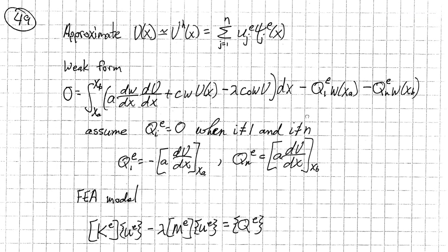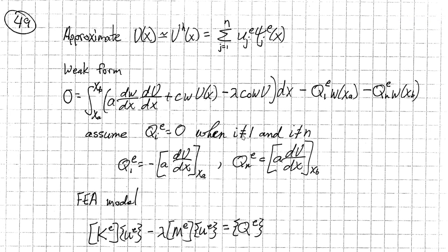So to continue on this heat transfer problem, again we're talking about approximating the solution as we've done in the past. We have some solution U, and it's the heat transfer problem, so this is our temperature. We approximate it over the finite element as a function of nodal solutions at the endpoints or nodes of a finite element and some type of function that interpolates between those nodes.